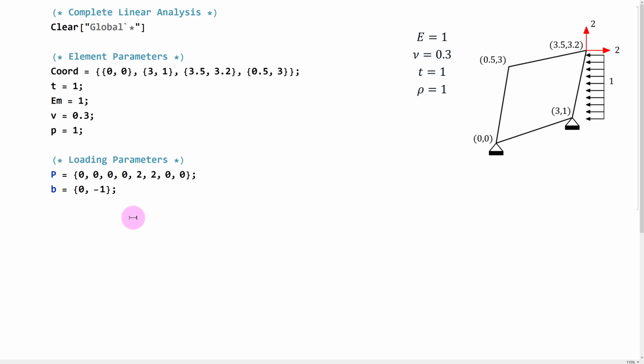But of course, we're going to have to modify this later on so that we can have our loads located at our nodes. And then finally, the other vector we talked about is a traction vector. So again, this would be things like a distributed load. If we look at our example here, we can see that we actually do have a distributed load acting on the surface between nodes 2 and 3, and it has a magnitude of -1. So in this case, our traction vector is equal to a vector with two components. The first is the horizontal component of this distributed load, which we know is -1. And the second is the vertical component of this distributed load, which we know is 0. So I'm just going to go -1, 0.